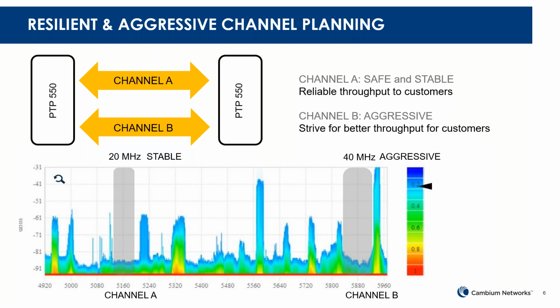For very high interference areas, we recommend going with higher performance. There are standard performance antennas and high performance antennas. Certain vendors also have ultra high performance antennas. All they do is make the antenna slope much sharper, so you will be able to get rid of the interference.